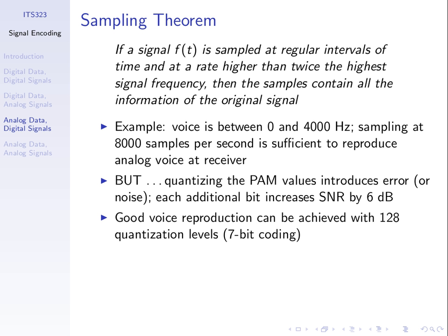What's an example of that? Audio, the example with CDs. One of our earlier slides, maybe in one of our first lectures, we had some plots that showed the spectrum of voice. When people talk, their voice ranges from several hundred hertz up to several thousand hertz, whereas music ranges from several hundred hertz up to maybe 10, 20,000 hertz. So when people create music, let's say the highest frequency component is 20,000 hertz, therefore the optimal sampling rate is twice that, 40,000 hertz. And that's why when they record audio CDs, not MP3 CDs, but audio CDs, they use a sampling rate of 44,100 hertz. It's twice the highest frequency component they expect to have in the audio music.